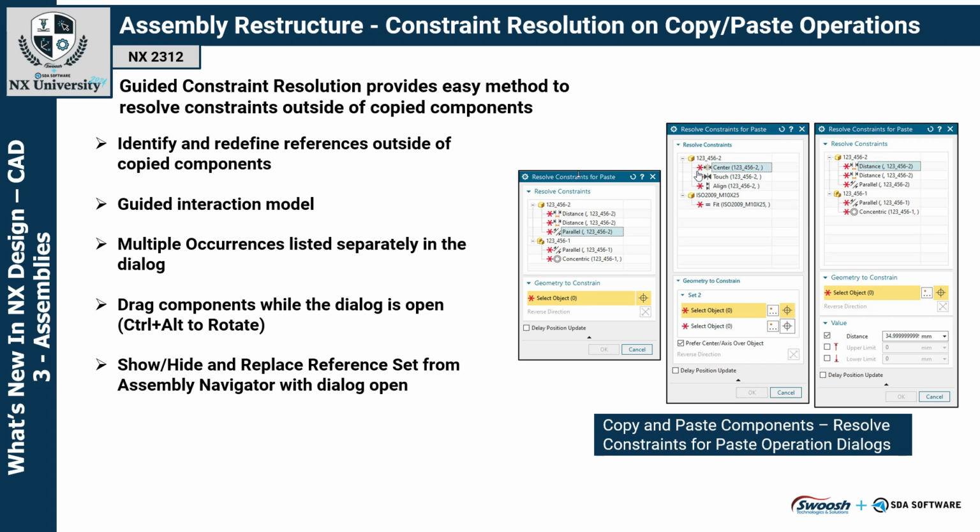You can show, hide, and replace reference set from Assembly Navigator with the dialog open. As you can see over on the right, there are going to be 3 different appearances of the resolve constraints for paste dialog, and we'll see that in the demonstration in a moment.